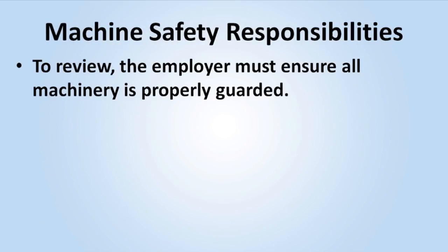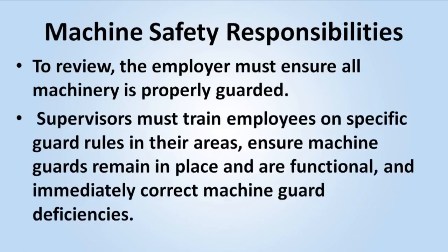To review, the employer must ensure all machinery is properly guarded. Supervisors must train employees on specific guard rules in their areas, ensure machine guards remain in place and are functional, and immediately correct machine guard deficiencies.